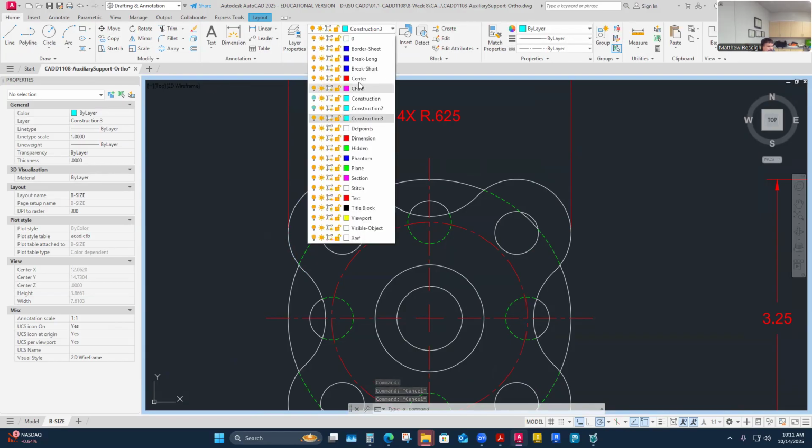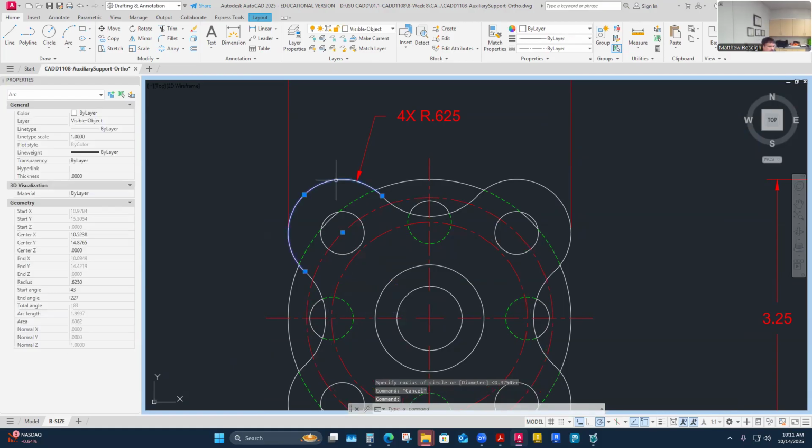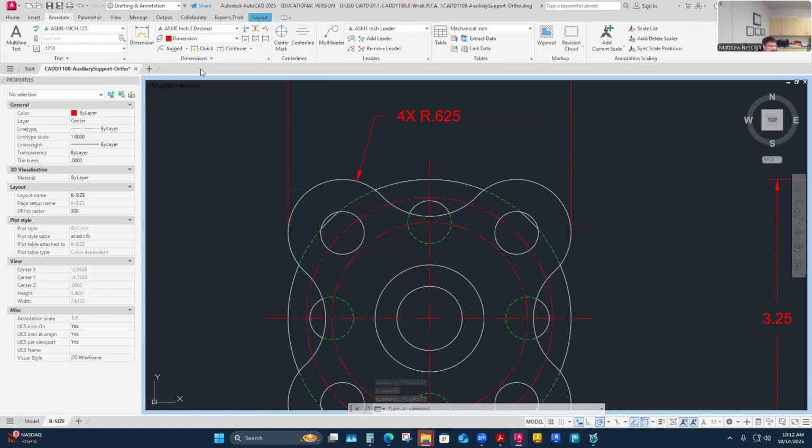another piece of geometry, a center circle based off the same center point. That axis is going to be a really good control for this thing. But I'm going to snap this circle, and the reason why is because really it's going to control location for this and for this as well. And so I have that as kind of a distance out, and it would have a dimension associated with it, right? Like a diameter dimension on a bolt circle.